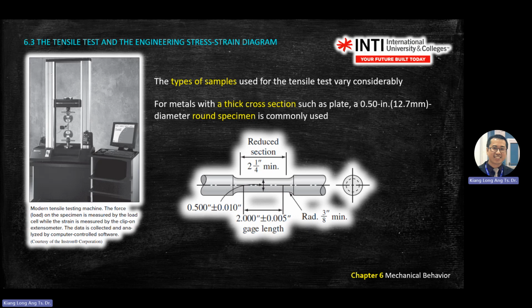This tolerance can cost you money if you're not careful, because the more decimal places, the better and more powerful a machine you need, because you need to cut more accurately in the process. For example, your phone casing, if you open up the button and all these things, they have a very high tolerance. If there is a difference of 0.01, you're not able to fit in the button and all these things.